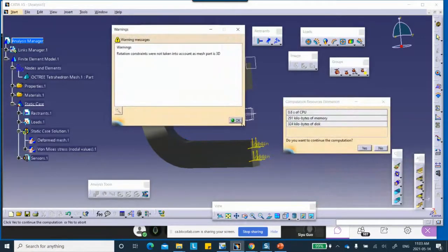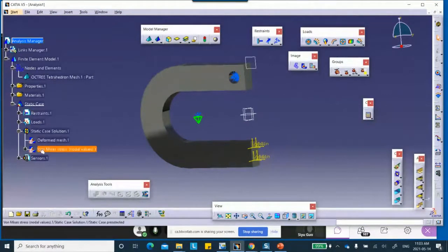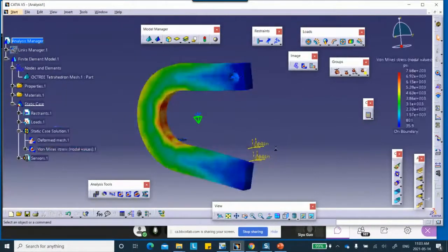Linears are cheaper, but less accurate. But it may not be 10%, may not be important to you. It was 9,000, right? It's more. This one is actually more than 10%. It went from 9,300 to 7,000. So if you were careless about doing a convergence study, you just made a run with linear element, looked at the result, and said, oh, the biggest stress is this. Well, that is bad because you're off about 15, 20% of what it should be. And that 15 to 20% could be getting it into the yield zone or not.